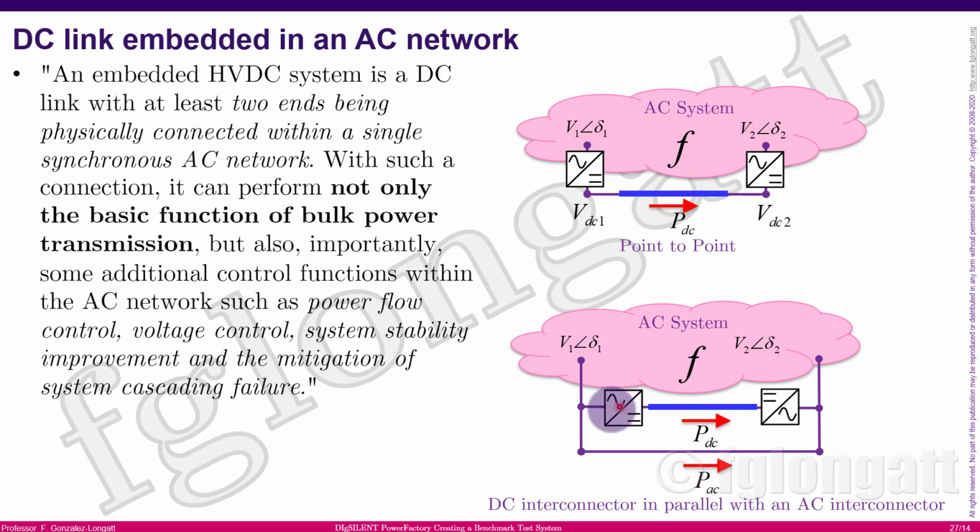But today I'll be working with one of these HVDC links that is in parallel with an AC link. The idea of having a DC transmission line in parallel with the AC link is basically to have better control of the active power that is moving on the AC side. AC has been in the electrical power system for many years. However, it has some limitations regarding the control of active and reactive power. And the DC link is coming to help in this kind of matter.